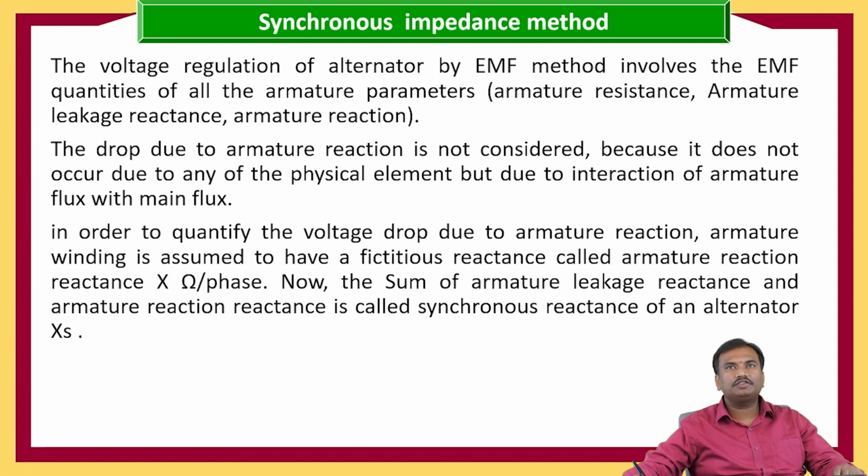So voltage regulation of an alternator by the EMF method involves the EMF quantities of all the armature parameters, where the armature parameters are armature resistance, armature reactance, and armature reaction.